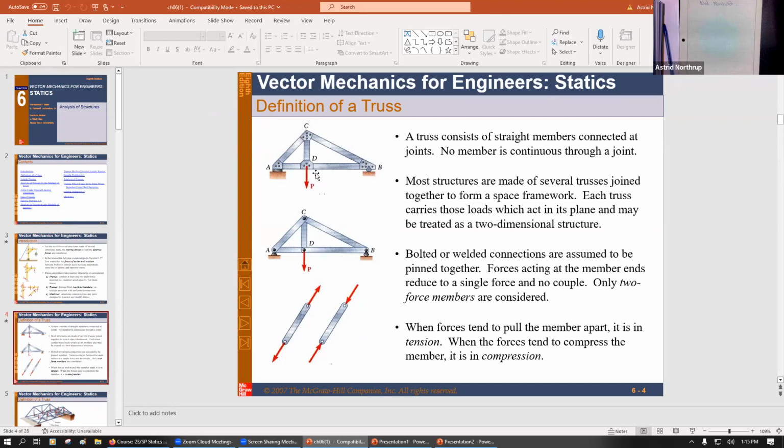as well. Now, the other thing is, this isn't really brought out in this class. You'll talk more about this when you take mechanics of materials, but certain types of internal forces tend to be borne at connections. So, for example, this truss is drawn with a gusset plate that is heavily bolted or riveted at those connections, because that's really where certain kinds of stresses concentrate. So we'll talk about that more later. But once again, if you look at the entire truss, or if you look at part of the truss, everything has to sum to zero.